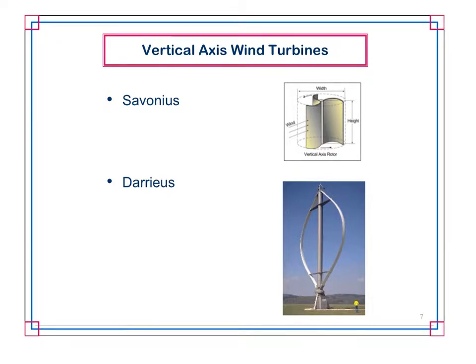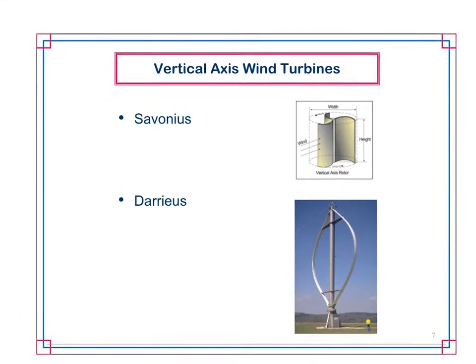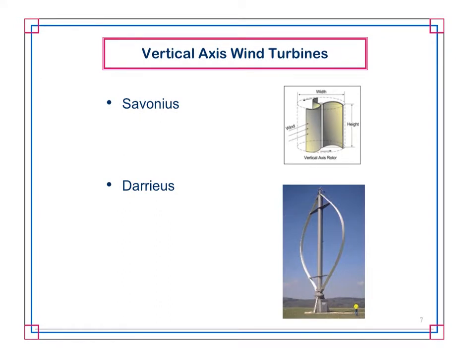A little hard to see, but what makes the vertical axis wind turbine so cheap is all the weight is at the ground level. So when you erect these wind turbines, you need to think about how expensive is it to erect it. Well, if the heaviest piece of machinery is at the ground, to erect it you need a small crane, right? And then you can almost have a tall crane, but it doesn't have to have the capacity to actually be able to erect this thing.